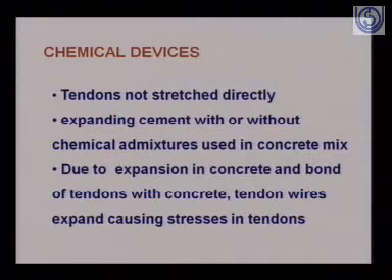When we are casting the structural member, we use expanding cement with or without chemical admixtures. What is the action? On setting, the concrete tries to expand, and in that situation the strands which you have already provided in the structural member will elongate along with it, and by this process tensile stresses will be developed in the tendon.